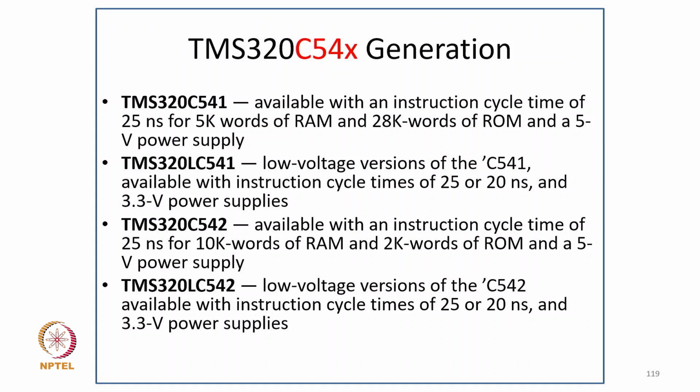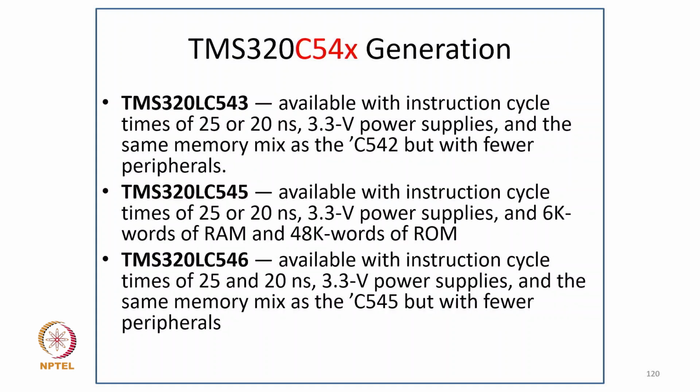TMS320C542, available with an instruction cycle time of 25 nanosecond, 10K words of RAM and 2K words of ROM and a 5 volt power supply. And TMS320LC542, a low voltage version of C542, available with instruction cycle times of 25 or 20 nanosecond and a 3.3 volt power supply. Now coming to